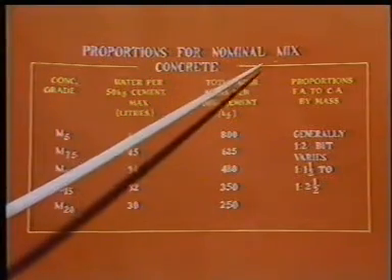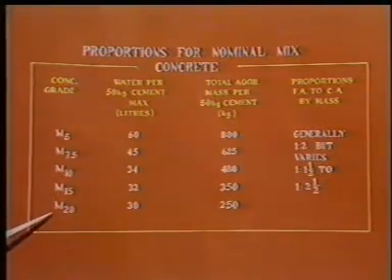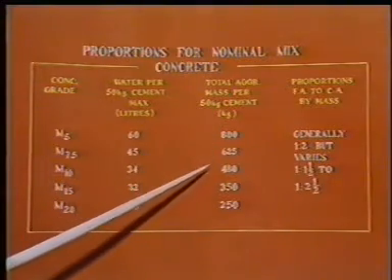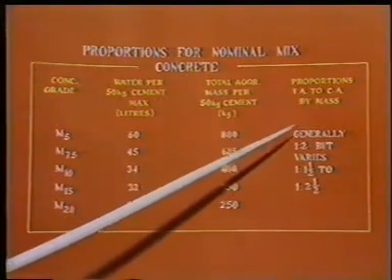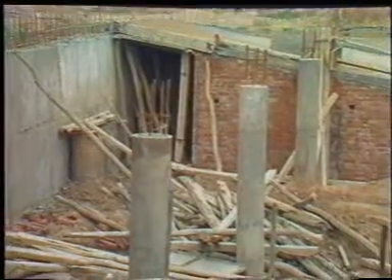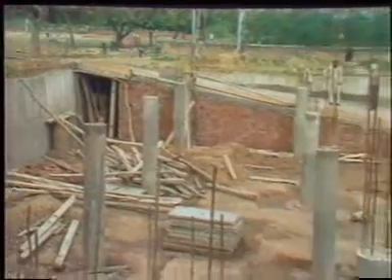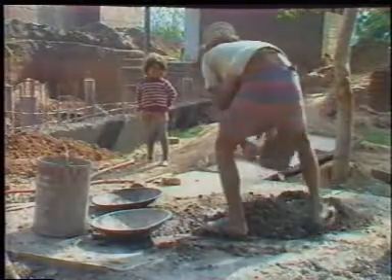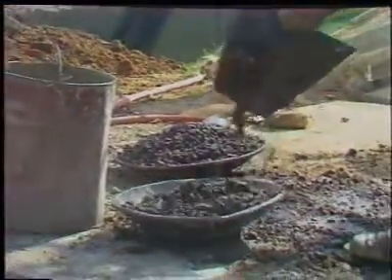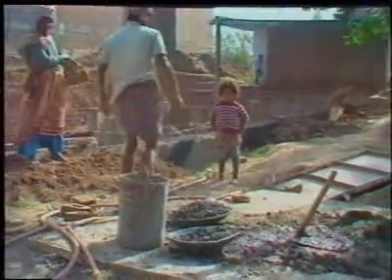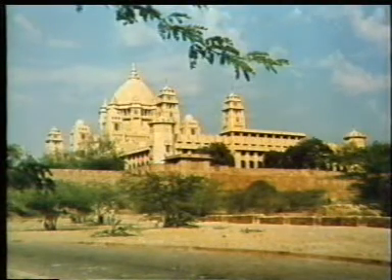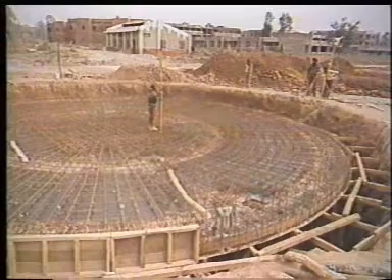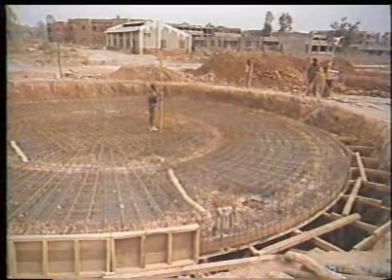Cement concrete mixes may be prepared as nominal mixes, that is ordinary concrete, or as design mixes, controlled concrete. Nominal mix proportions are not based on rigorous testing, but are based on experience and approximations. These proportions may be used for small and less important jobs only. For important and large jobs, it is necessary to design the concrete mixes on sound scientific principles of water-cement ratio, workability, etc.